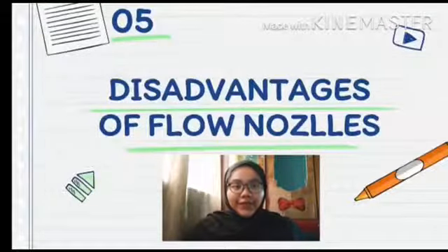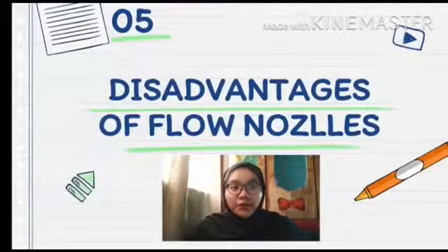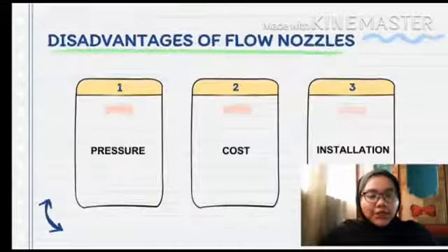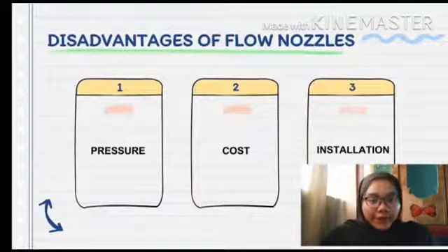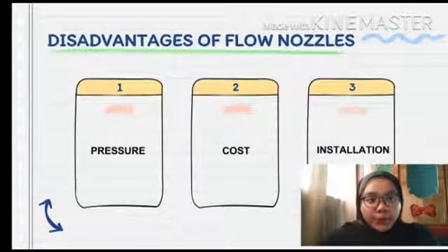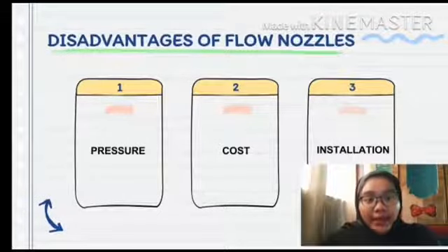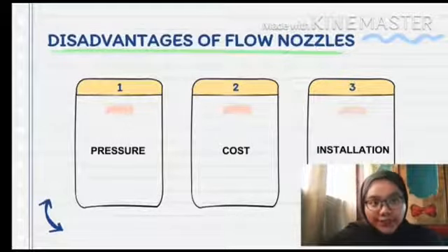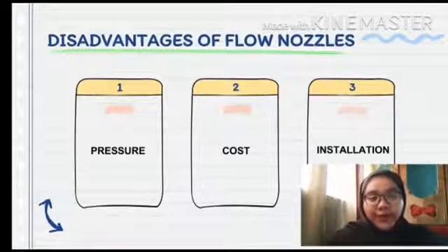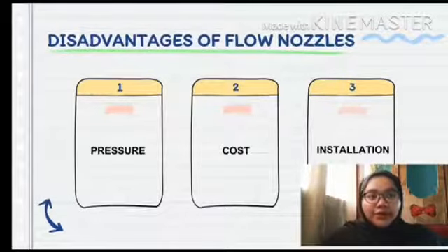Next, I will continue with the disadvantages of flow nozzle. The first disadvantage of flow nozzle is it has low pressure recovery. Second, it has high maintenance. Third, installing the flow nozzle compared to the orifice is quite difficult.